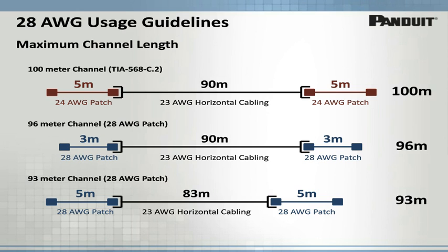No. That's actually, again, another great question. Thank you all very much. The simple answer to that is no, in that whether using the standard RJ45 jacks that you would find terminated to 23 and 24 gauge cabling, or even if you happen to make an equipment cord out of a 28 gauge patch cord and use a 28 gauge jack, that allowance in the channel for up to 4 connectors in the channel of the insertion loss, that allowance is already dealt with in the 100 meter standard. Allowable configurations covered by the standard at 100 meters are 2, 3, or 4 connector configurations. So essentially the simple answer is no, because that allowance for insertion loss by the added connectors is already built into the standard. And I hope that is clear there.